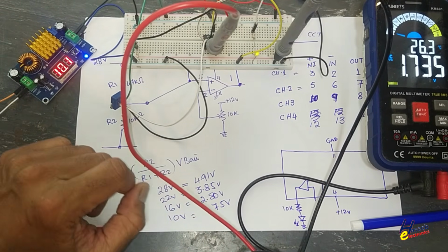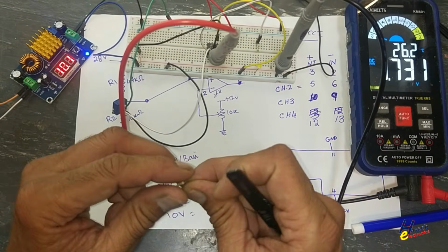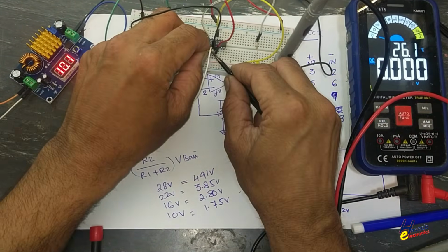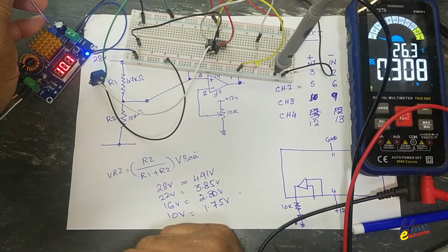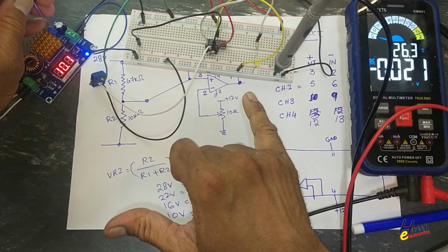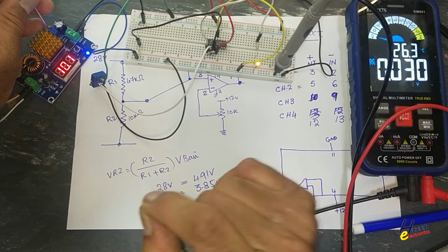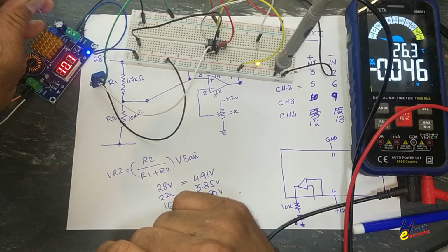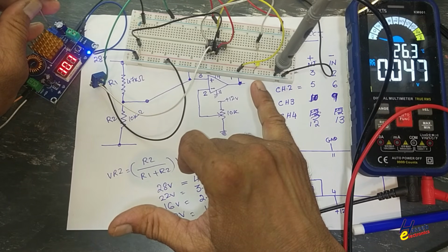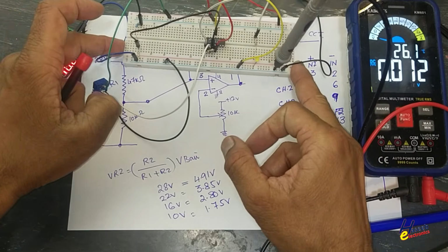So best way to use 1 mega ohm resistor, as I discussed here, between pin number 1 and pin number 3. Now when voltage level will be obtained properly, the LED will turn on. This time there is no flickering. It is effect of 1 mega ohm feedback resistor.